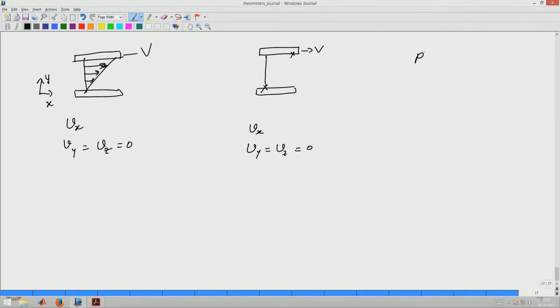So, generally in such cases what we say in rheometry is that the plate separation should be at least 10 times the particle size. Generally, if we are ensuring this, then the local variations, because a particle is there or not there, will all average out, and linear velocity profile is still very good in terms of giving us the bulk behavior of materials. So, generally we will still get bulk behavior even though the sample itself is heterogeneous at microscopic scale.